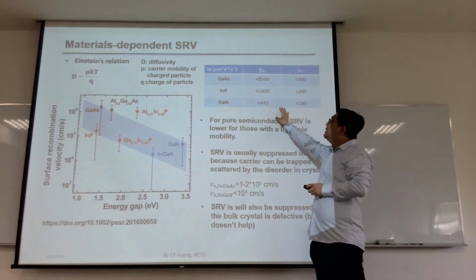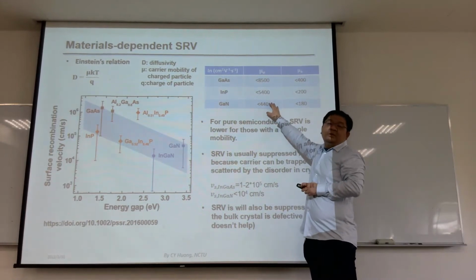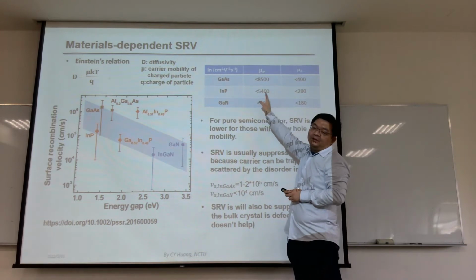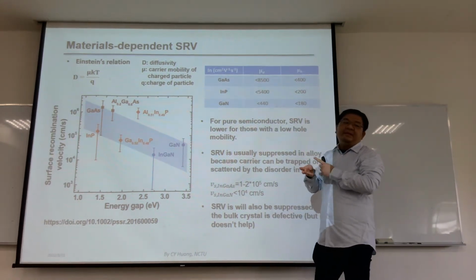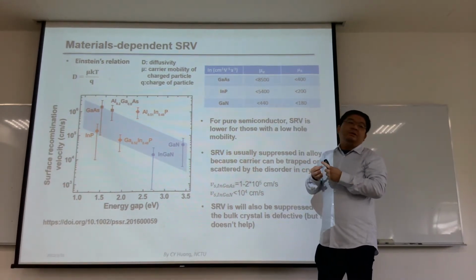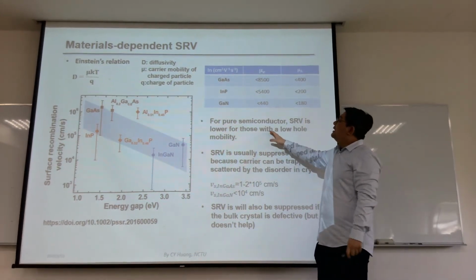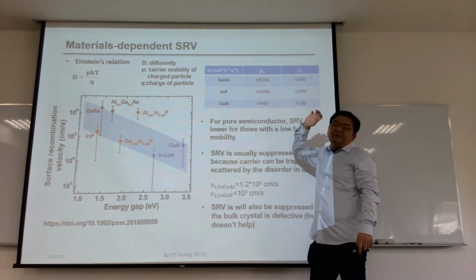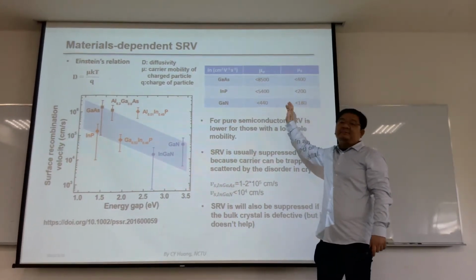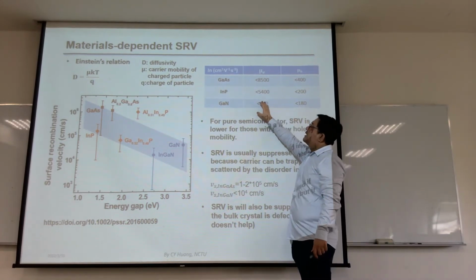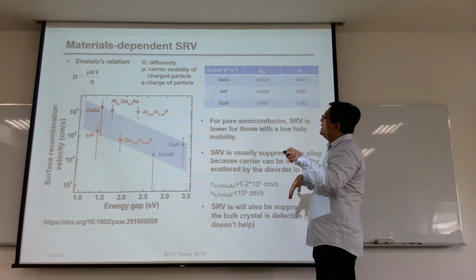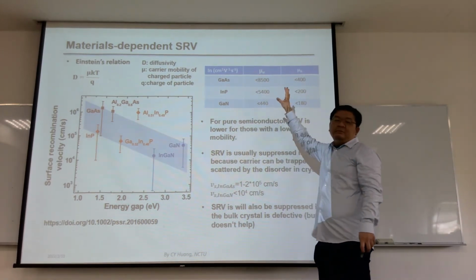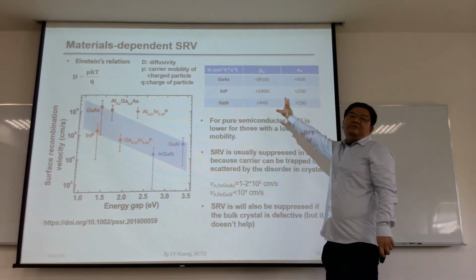It's usually also doping and quality dependent. The higher the mobility, the better the crystal quality, or the lower the doping level. Anyway, some might get 400, 500, maybe even 600 is possible in a very good crystal. But compared to gallium arsenide or indium phosphide, the value is only 1/10 for the carrier mobility.